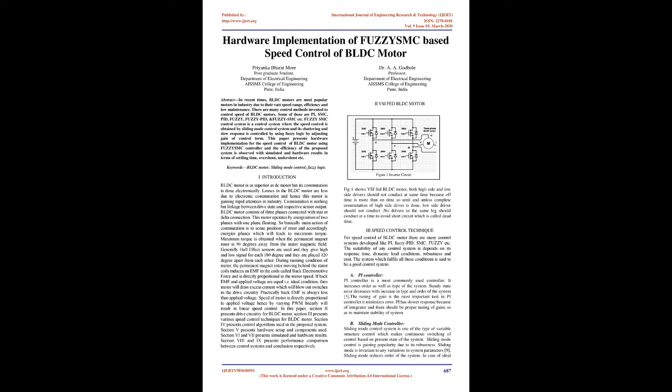FUZZY-SMC control system is a control system where the speed control is obtained by a sliding mode control system, and its chattering and slow response are controlled by using fuzzy logic by adjusting the gain of the control term. This paper presents hardware implementation for the speed control of BLDC motor using FUZZY-SMC controller, and the efficiency of the proposed system is observed with simulated and hardware results in terms of settling time, overshoot, undershoot, etc. Keywords: BLDC motor, sliding mode control, fuzzy logic.